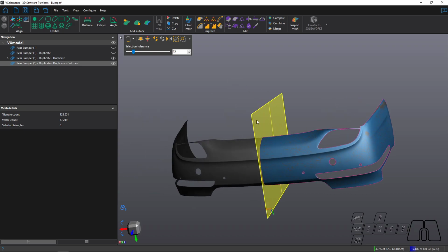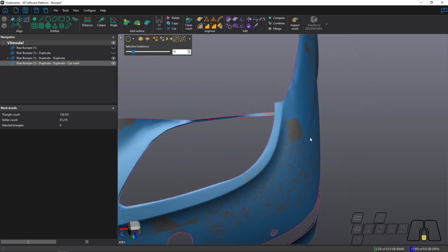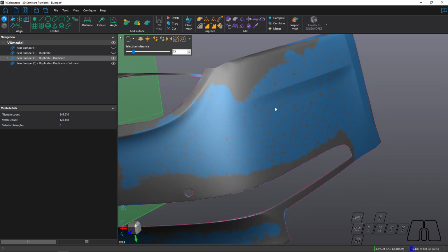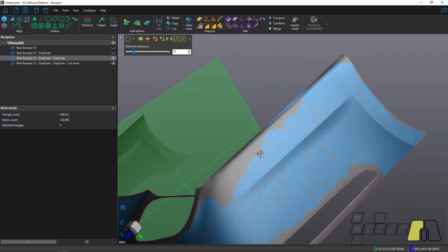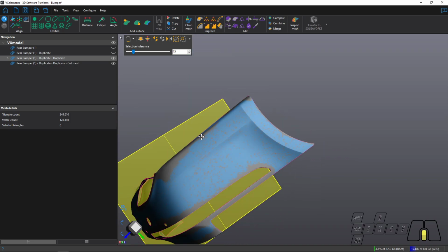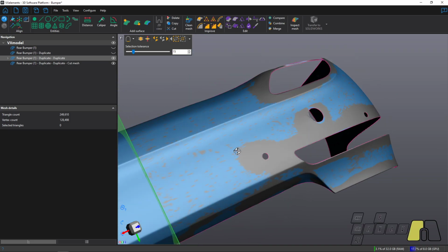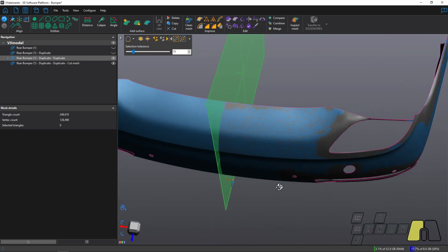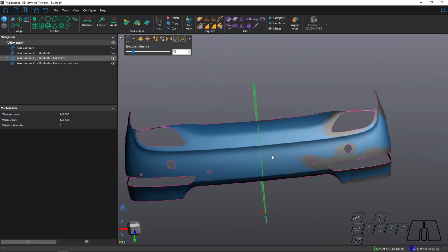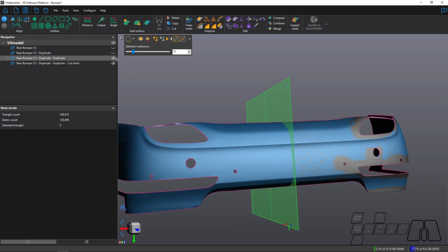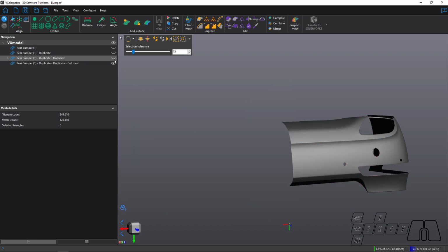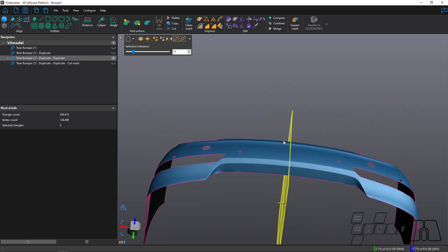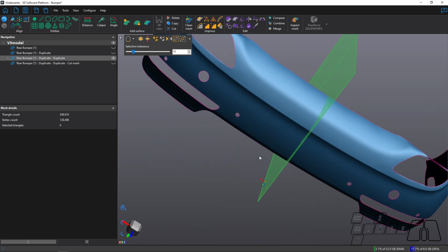So if we compare this with the one that we took out, which in this case is in gray, that means that we're good. Yeah, the symmetry plane worked very well because we don't see any potential deviation between pieces. So that looks great. Okay, right on. So now that I have mirrored my mesh, everything looks very promising for the flattening process.